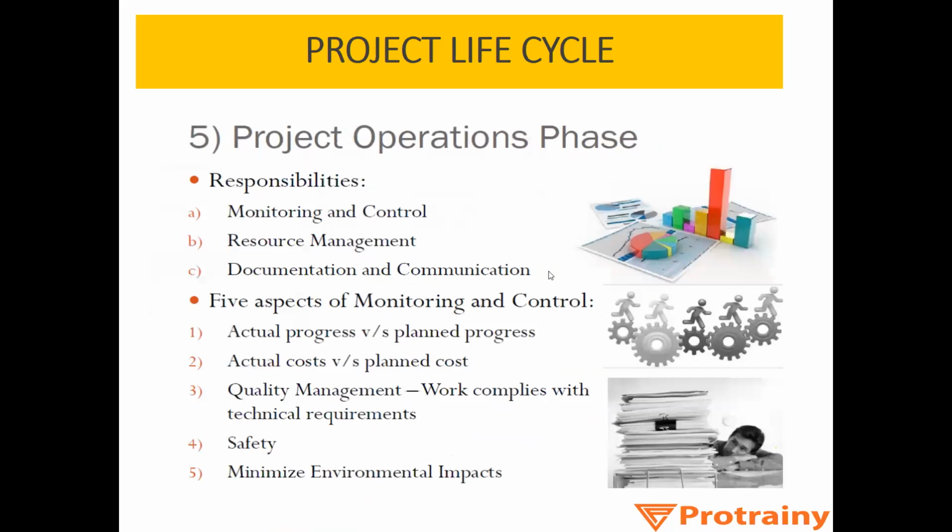Now the fifth phase is the project operation phase, when the work actually starts. So what are the responsibilities of a construction manager in this phase? His responsibilities are monitoring and control of the project, managing all the resources, that is resource management, documentation and communication. Then the final aspects of monitoring and control are preparing actual progress versus planned progress, actual cost versus planned cost. Then quality management, that is whether work complies with technical requirements or not, safety of your labor and engineers, and minimizing environmental impact.